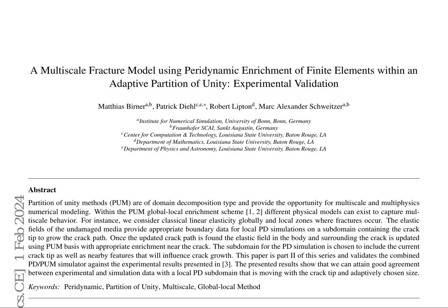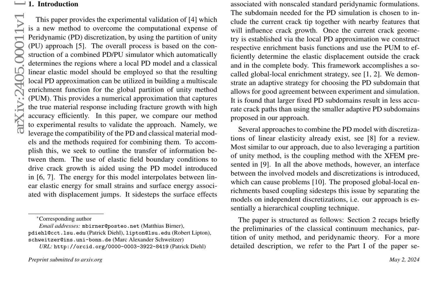Here, the authors focus on experimental validation of the proposed method, comparing simulation results with experimental data. By leveraging the compatibility of peridynamic and classical material models, as well as the methods required for combining them, the authors achieve high accuracy in capturing fracture growth. The peridynamic model interpolates between linear elastic energy for small strains and surface energy associated with displacement jumps, thereby sidestepping surface effects associated with non-scaled standard peridynamic formulations.